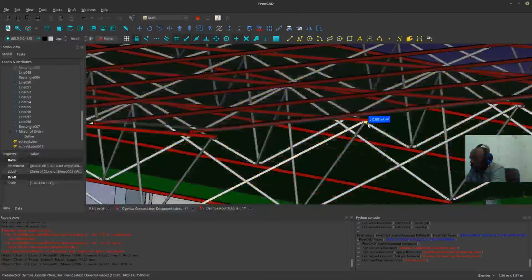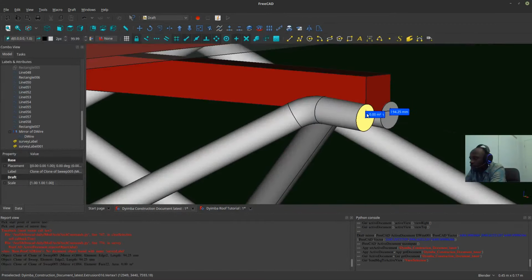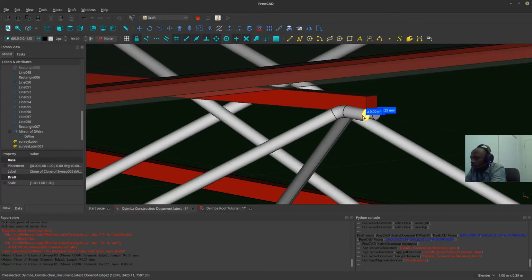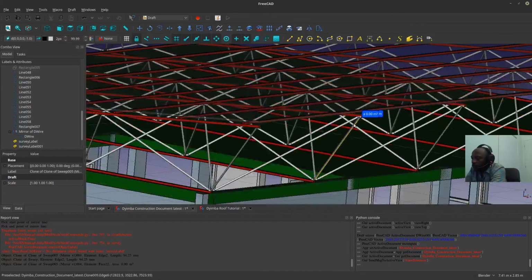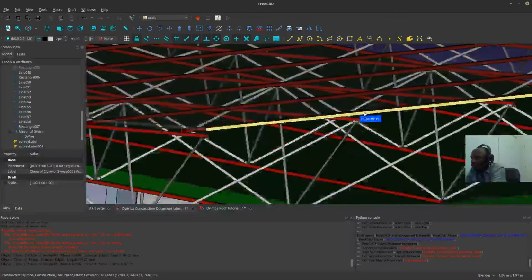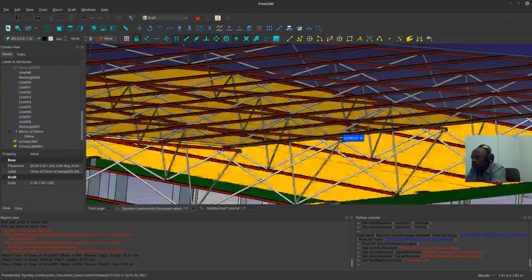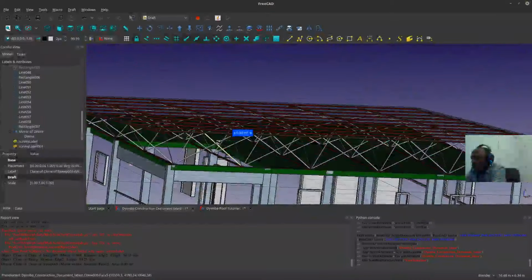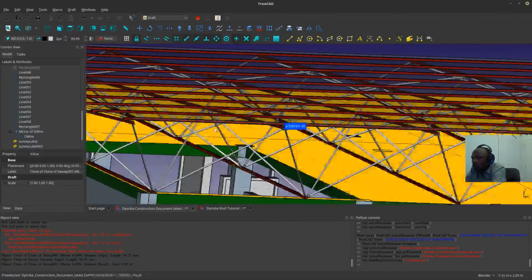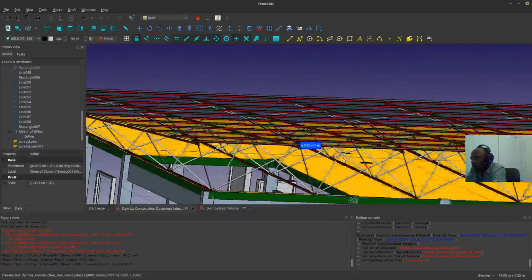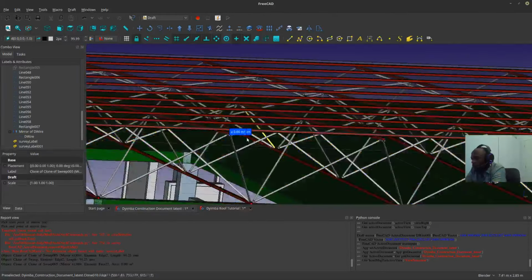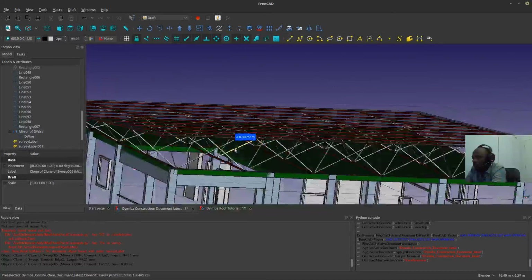In this scenario, I had to create the circle on the face. It had to be perpendicular like that. So the advantage of that is that with the circle you can always control the radius, and what you do is that now you clone all of these objects. So with one of these objects you mirror it on the side, and then you can clone it all along, and so it makes that one object can modify everybody else. Let me show you what I mean.